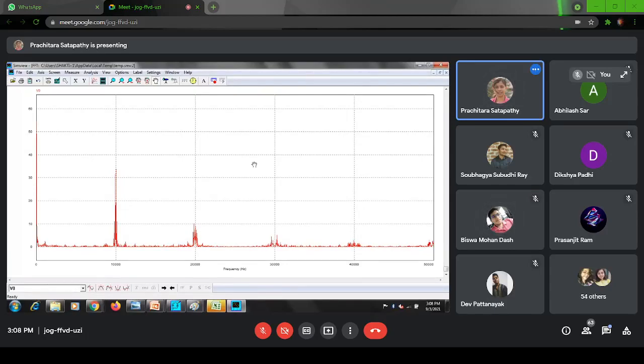And 5000 you have taken frequency of what? Carrier. Carrier frequency is 5000, FC. So harmonics are present in the V0 waveform. 10,000. You can see at 10,000 hertz here. Then 20,000. So that means if F is 5,000, it is 2F. It is 4F. It is 6F. Yes or no? 8F. Like this. Yes or no?